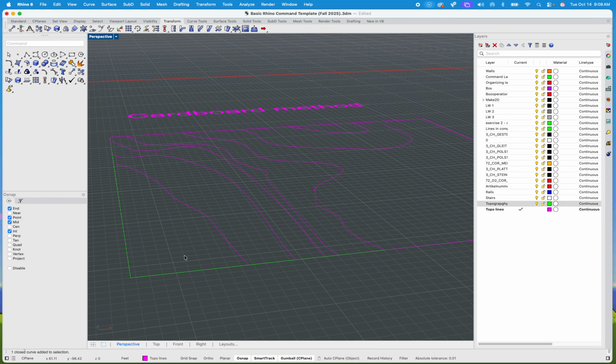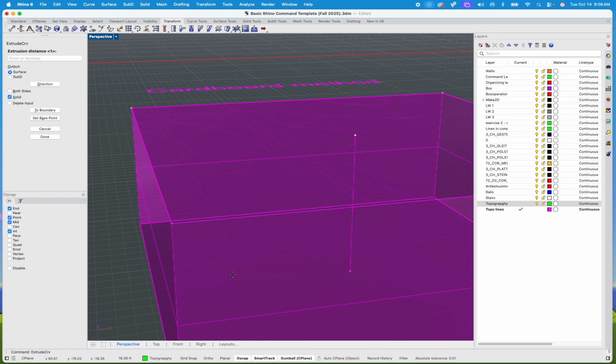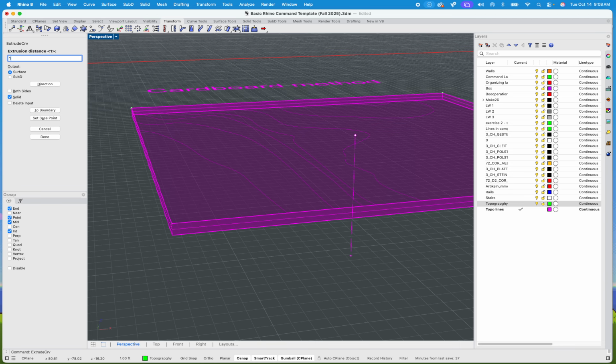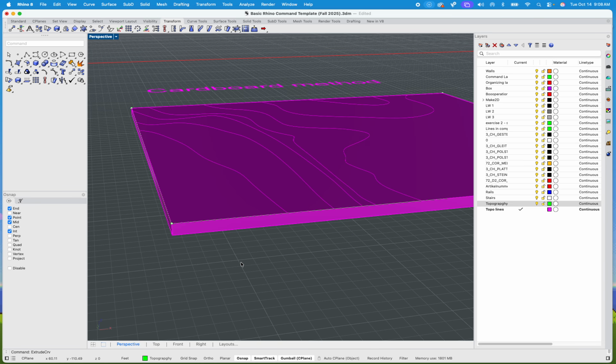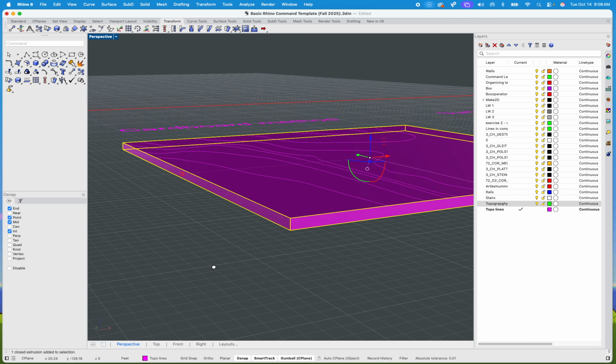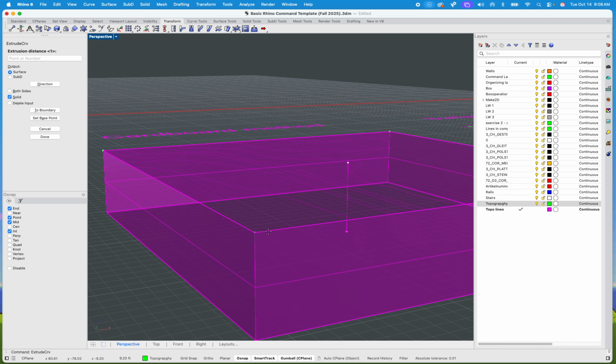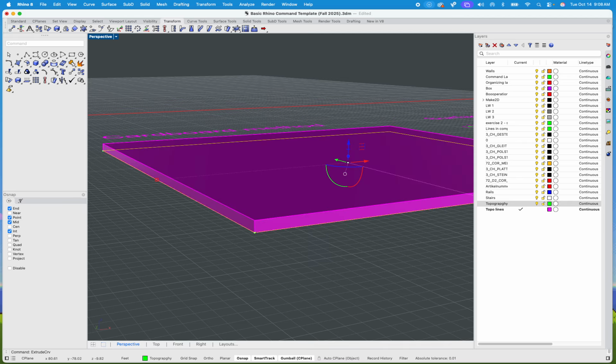No, I'm just kidding. But in our case, let's go ahead and build the topography. And each of those layers we know is going to be 1 foot. So of course I'm going to extrude it. This will be my base. And it'll be 12 inches or 1 foot, right? So I can type in 1 foot, enter. Voila, we have our base layer. To be fair, that basically went up, right, because I typed in 1 foot. Now if I type in -1 foot, equally it actually goes down. So if I type in -1, it should have gone down.